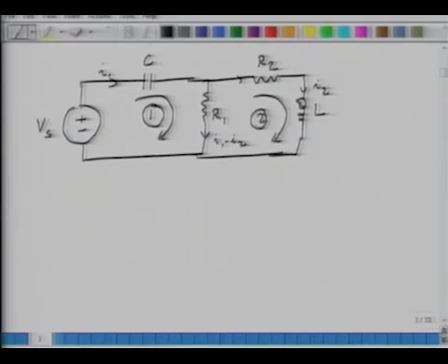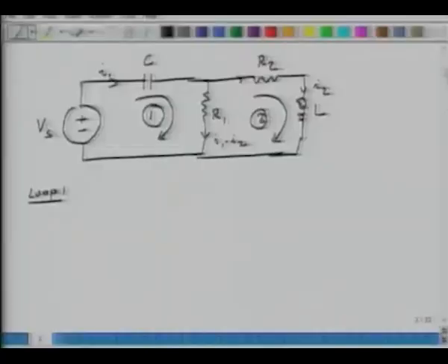Because I have an external voltage source, I'll try to solve this problem using Kirchhoff's voltage conservation laws. I'll apply that law for loop 1 and for loop 2, so I will get two equations. I have two variables, I1 and I2, so I can solve for two. For loop 1, I first move to frequency space by mapping these into their impedances.